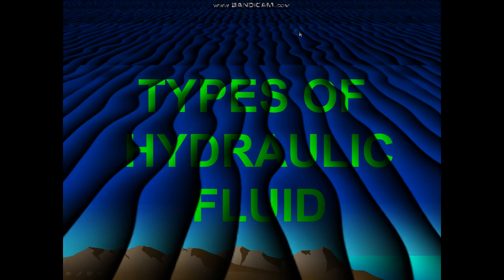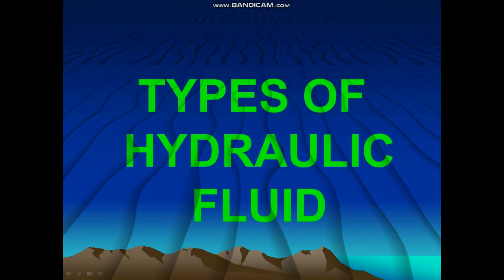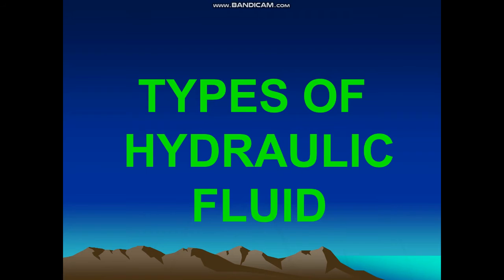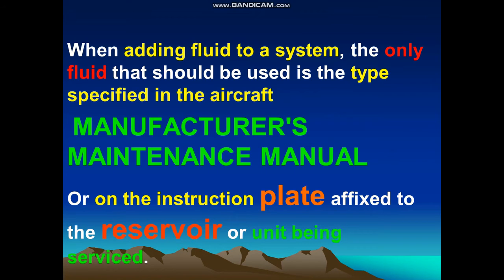Now we will talk about the types of hydraulic fluid. When adding fluid to a system, the only fluid that should be used is the type specified in the aircraft manufacturer's maintenance manual or on the instruction plate affixed to the reservoir or the unit being serviced.